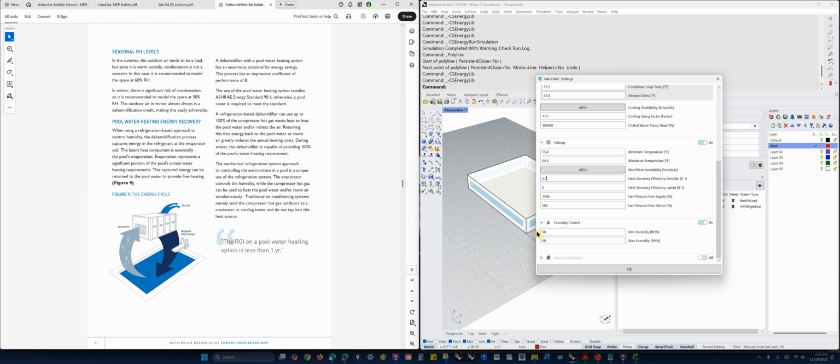But this is the big one that I changed. The typical default here is 20 to 80%, and that's basically the comfort zone. I mean, 20 is really low, but you would not be in danger, at least if you were in that zone. What the 90.1 guidelines are saying is that we should keep the humidity between 50 and 60%. So you'll see that's going to change things quite a bit. Also, that's very different than what other zones would be.